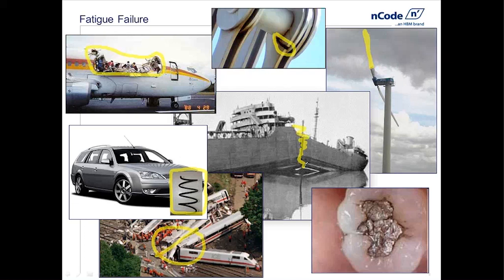So in this case, the riveted joint, if a crack would start, it would not be able to pass through the lap joint into the adjoining member. However, with a weld, that is not the case, so this lacked the ability to deal with a crack, or to blunt the crack, or to stop the crack. This is not a fail-safe design. As you can see, this boat is seriously injured.